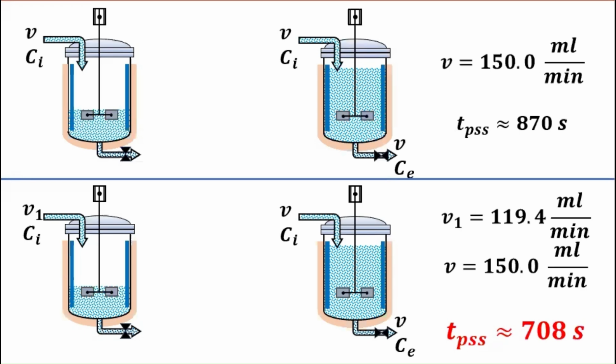In other words, if we want to complete all the experiment stages on time, the reactor must be filled at a rate such that at the moment of filling, the ethyl acetate concentration is equal to the practical steady-state concentration, based on the selected volumetric flow rate, in the second stage. Investigating the kinetics of the ethyl acetate saponification reaction is one of the cases where students spend a lot of time performing all the stages of the experiment, and the reason for this is that in most instructions, the method of performing and selecting the experiment parameters is not selected correctly, and no optimization is done in conducting the experiments.